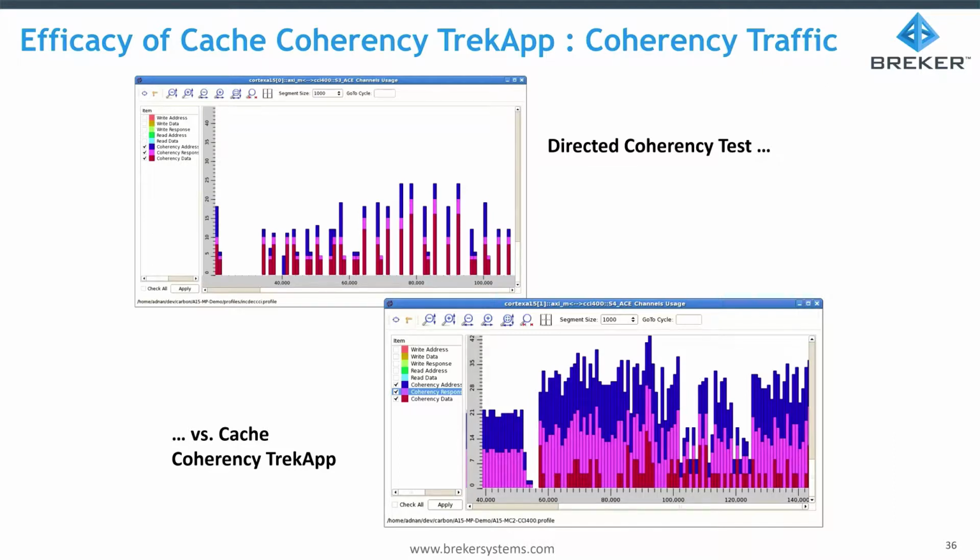How good are these test cases? So this is data from an ARM-based system, looking at ARM cycle-accurate simulations. And we were able to profile what was going on in just the coherency channel of the ACE fabric. That means that the reads and writes have all been filtered out, right? And we looked at the results from a very good coherency-oriented scenario that was created internally by the customer.